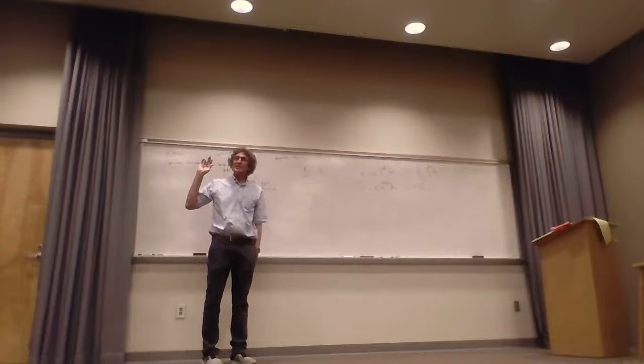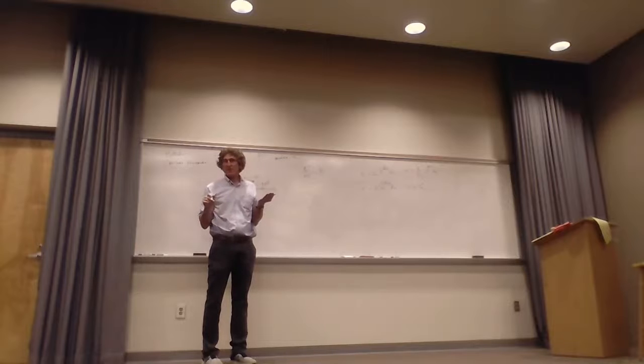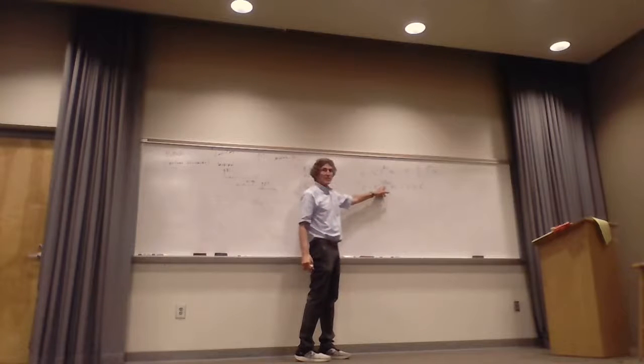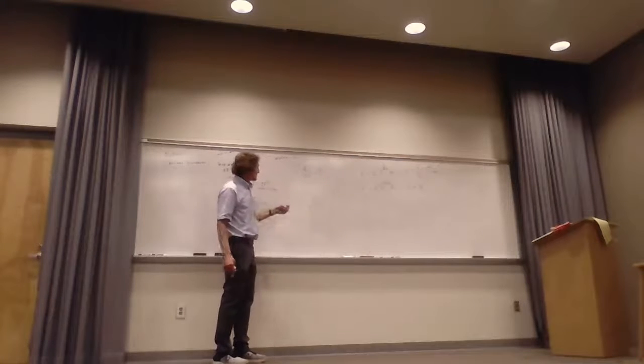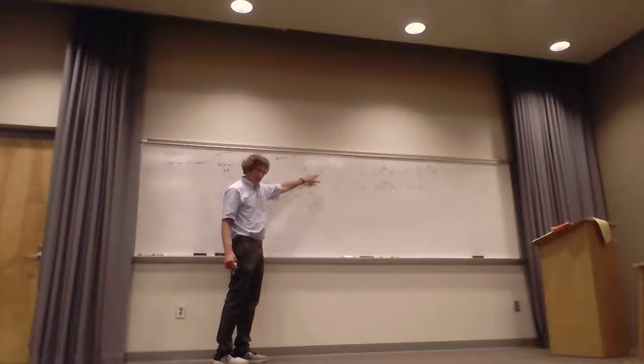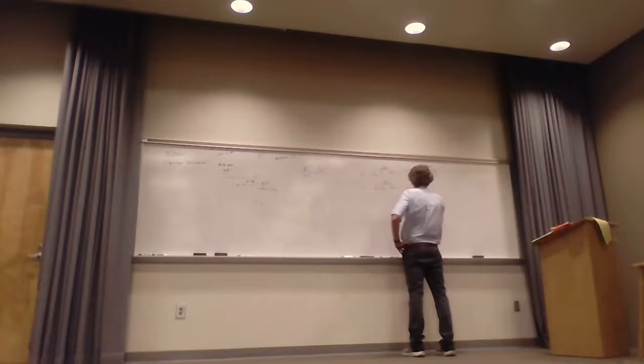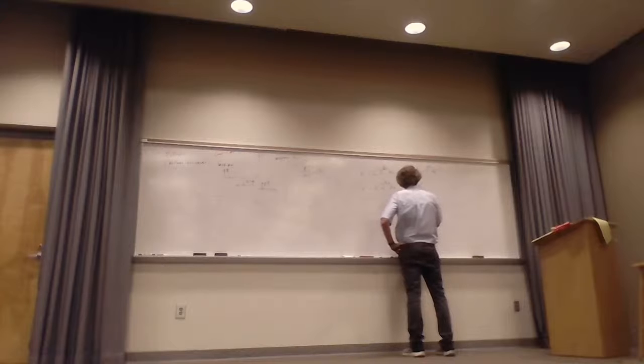Well, the reason it comes out to be a minus, if you go through the equations, the curl of E equations, when you have a wave traveling in the negative direction, you take the curl, it pops out a positive j, not a negative j. The ratio of the two will be negative. Just trust me on this one. So that means the reflected field is going to have minus E naught reflected, circle that minus sign, over eta 1 e to the plus j beta 1 z in the AY direction.